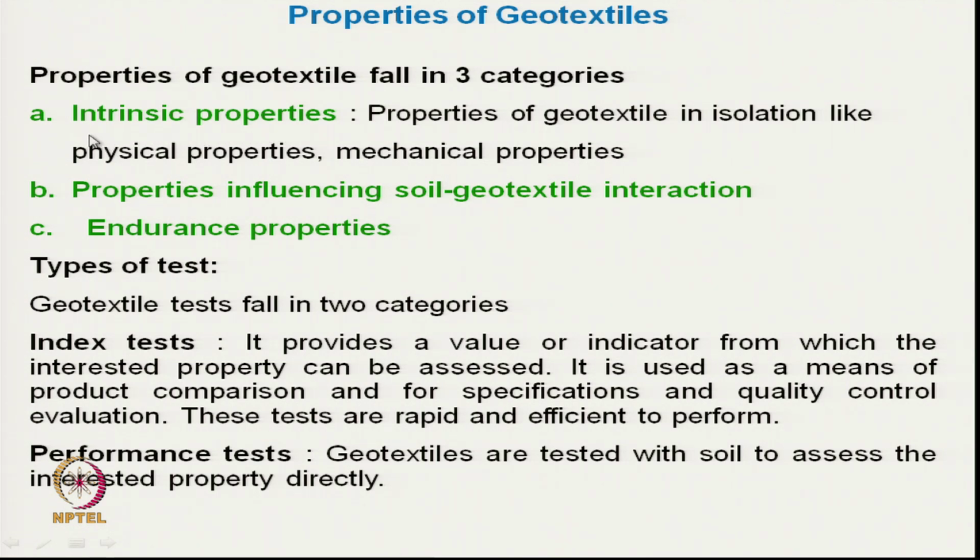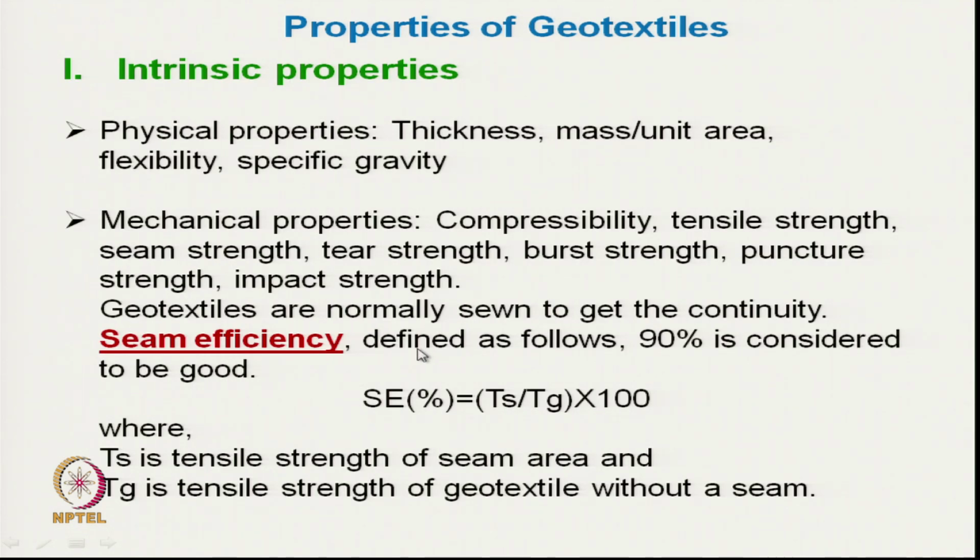These intrinsic properties are like physical properties, mechanical properties or hydraulic properties. The physical properties are thickness, mass per unit area, flexibility, specific gravity. Mechanical properties are tensile strength, seam strength, tear strength, bursting strength, related to all the mechanical behavior of geotextiles, and impact strength.